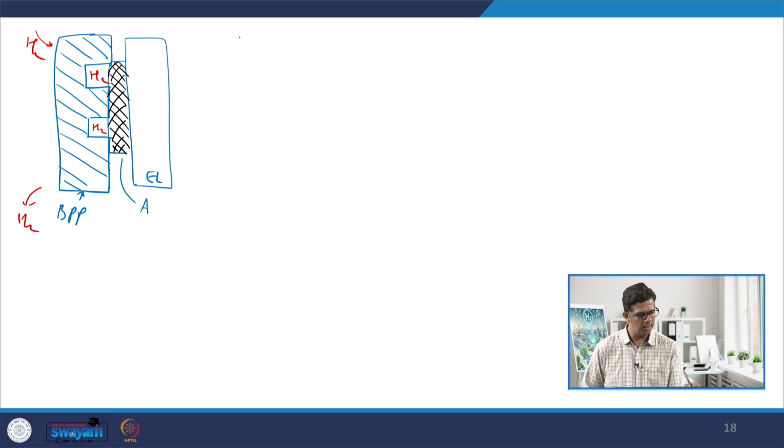As we understand, these bipolar plates are directly in contact with the diffusion layer. As we can see here, they are directly touching the diffusion layer. So electrons basically move towards the GDL, or move away from the GDL towards the bipolar plate, depending upon which compartment we are talking about. If it's the hydrogen side, the electrons will jump from the diffusion layer towards the bipolar plate.